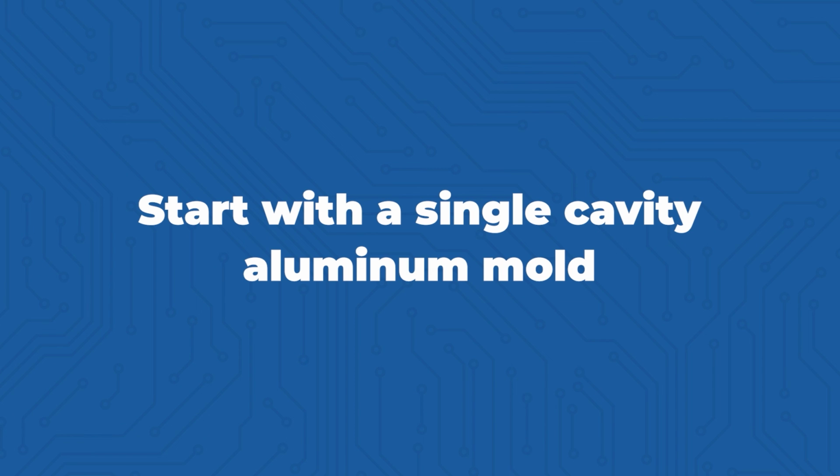Aluminum for the mold is important because it drastically lowers the cost of the mold, because aluminum, as you probably know, is a lot softer than steel. It just makes the mold easier to manufacture, because molds are machined using CNC machining. So machining away or sculpting away aluminum is much easier and takes less time than it does to do that with steel. Start with a single cavity aluminum mold. And those can be good for thousands of units, even up to maybe 10,000 or more units you can get from aluminum molds. Start there.